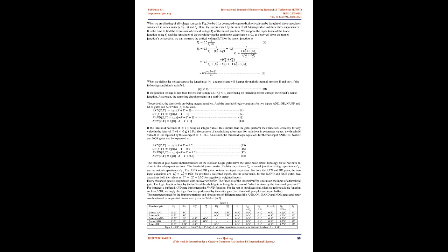The electric potential of the island can be tuned by a third electrode, called the gate, and the gate is capacitively coupled, through the gate capacitance, to the island. An extra capacitance C1 may intentionally be connected to the island for the purpose of manipulating the gate voltage, the input. The drain, source, and gate voltages are marked by V_d, V_s, and V_g respectively.